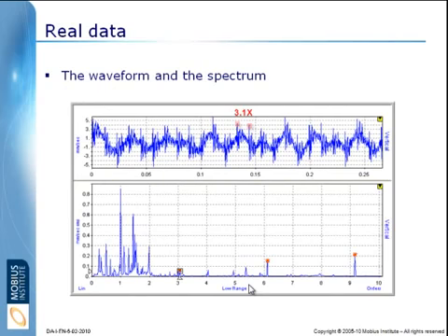Here is a real example of actual data from a machine that describes the same thing. Here is the time waveform, and we can see there's a low frequency here, which is the shaft rate, and then we can see an impact, impact, impact, impact, impact, impact, etc. These are repetitive hitting.